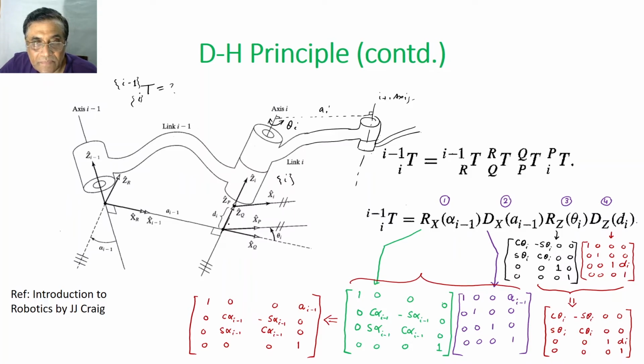So now it comes here, and earlier it was theta I rotation, now you give another operation so that it will be perfectly aligned here. So bring down along z, then rotate it about z by theta angle, so that now P will be like this. Okay, and then take the origin and translate it along the a I minus 1 axis here. So this PQ, and this we are calling R, just to tell you the full story. So you are snatching it like this.